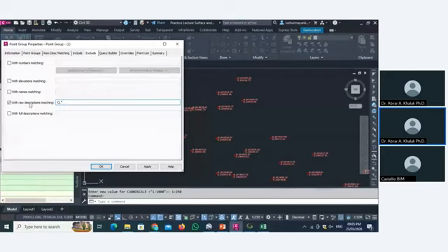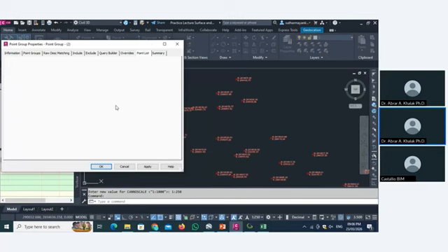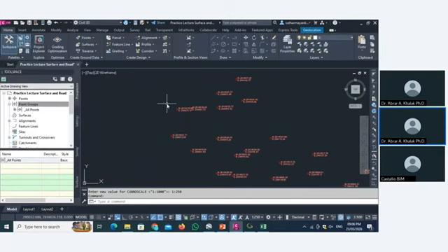Okay, if you click here and write down the description name, whatever the point name CL, that makes one group. If this option is not suitable for you, you can choose with elevation matching, with description matching, or with number. If you put the number here, it extracts the number. Whatever number you selected here, all are shown here in a point list.